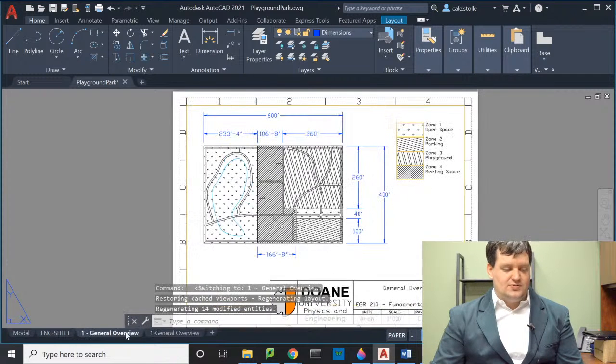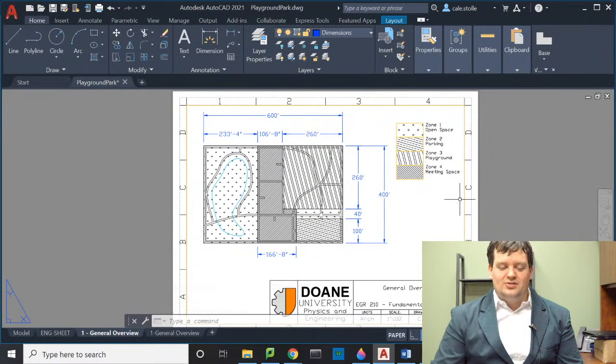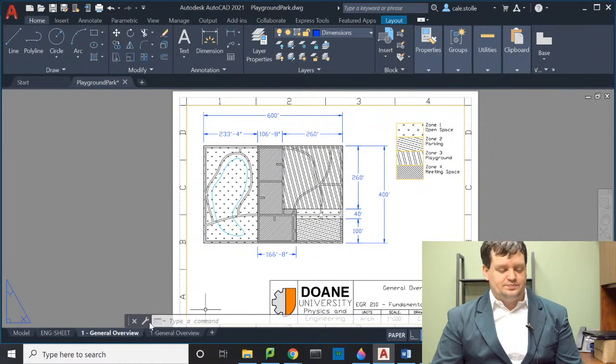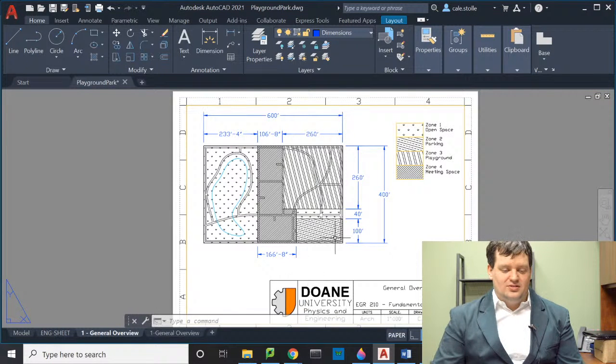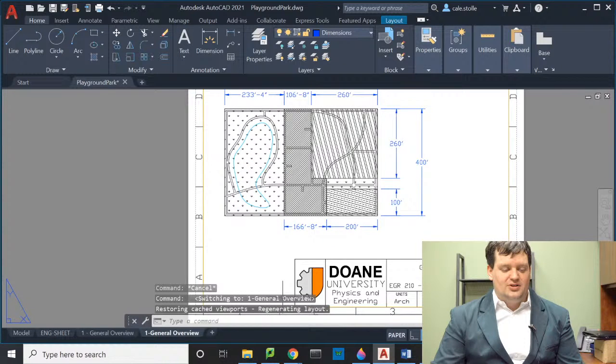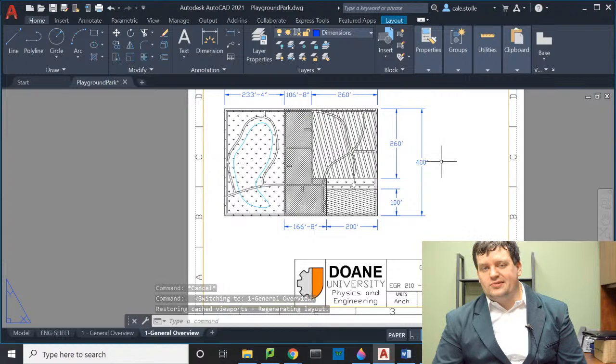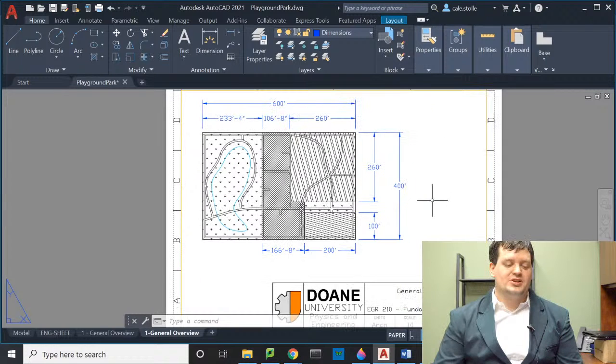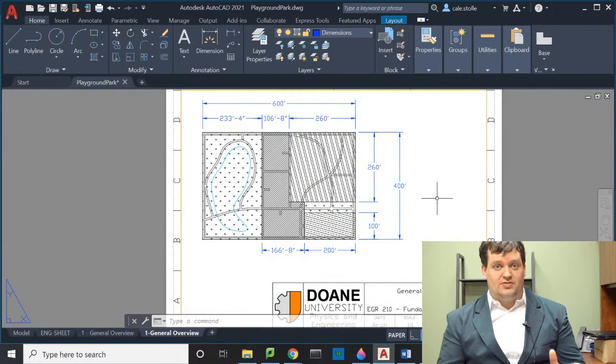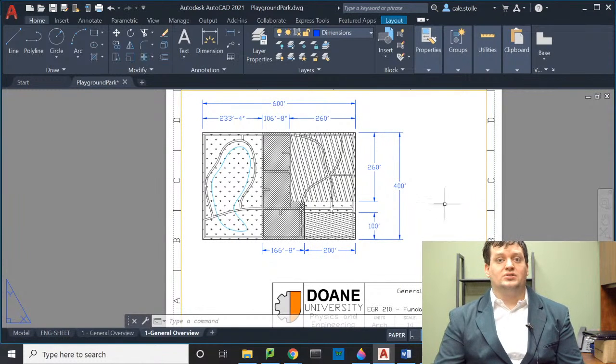As you'll notice, what I did for the other one, I just put them on the side there so that for reference I can figure out what those look like. You'll notice on this one I actually did do the 40 feet. I didn't dimension the parking lot here, but whatever. There's not one right way to dimension any drawing. As long as you can get all the information efficiently, effectively, and in a very clean fashion, you can dimension the way that makes the most sense to you.